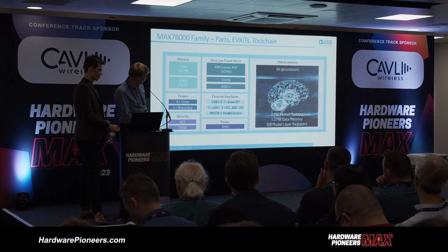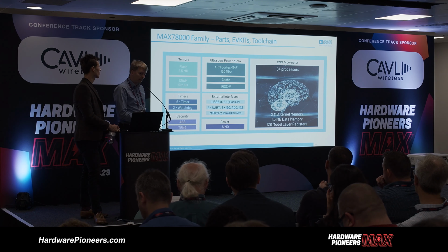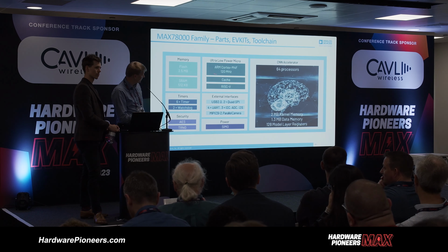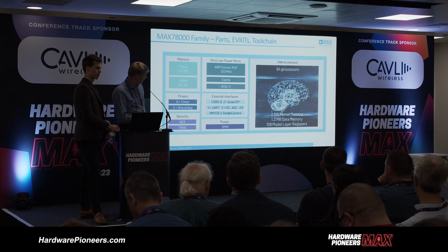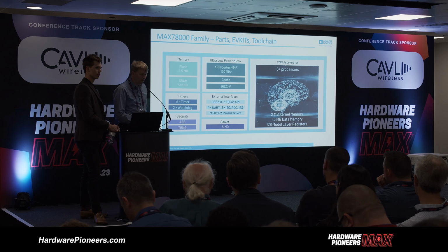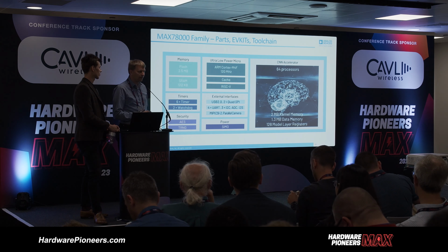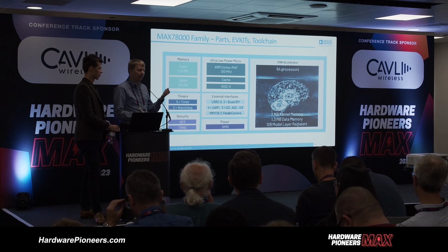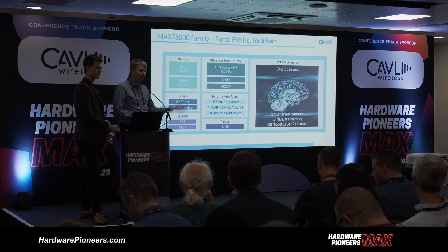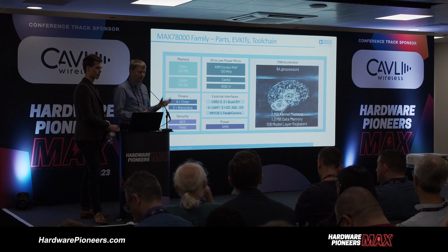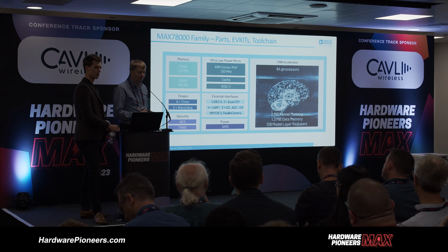So actually, this is a dual core MCU part, which has the ARM core, and we have included a RISC-V core as well. The main purpose of that is that you can use, for instance, the RISC-V core for moving image data into the CNN structure and pulling out the results afterwards, without utilizing the ARM core. So you can put the ARM core to sleep during that time. It's not symmetric multiprocessing, is it? No, it's not. Okay. Thank you.